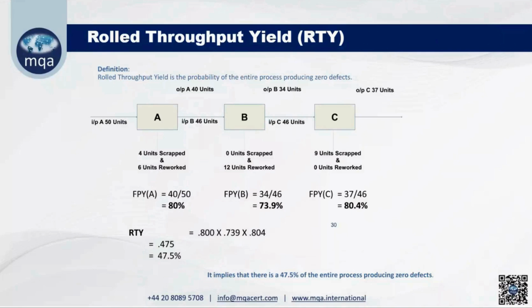So we use the term rolled throughput yield. Because at company level, an owner of the company will never see what is the yield of A or B or C. What he is more interested in is, what is my final yield. So finally, I am getting 0.8 into 0.739 into 0.84. So total rolled throughput yield is 47.5%, which is very bad. This is why we measure it. So now we know where we are. We are at 47.5% in terms of machine A, machine B, machine C. So this is the measurement.